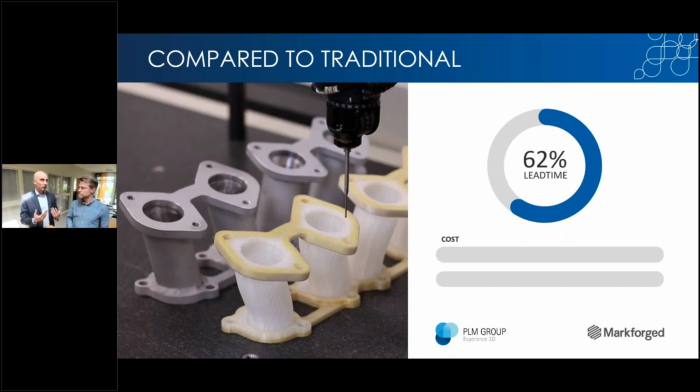Great. And that in and of itself is quite good. But looking at the cost to produce this in aluminium compared to 3D printing it, well, you have the numbers there. So 2,600 euros for one part, and to print it is 54 euros. Yeah, that's a huge difference. So this is a really good example of bringing prototypes and functional testing in-house really cheap, and also reducing lead time. This is something we see all across the board. Everyone who uses 3D printing for prototyping sees these numbers.